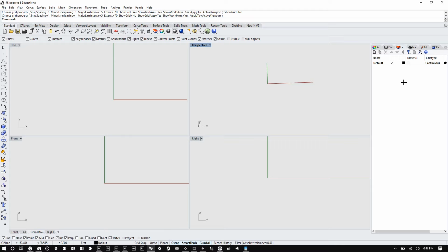If you're working with a surface and that surface is the ground, have that on a different layer than your glass and steel and concrete. Please, dear God, make a different layer for every type of object because materiality is tied to layers. So if you want your glass to be transparent, but you don't want your floor to be transparent, have them on different layers, for God's sake.